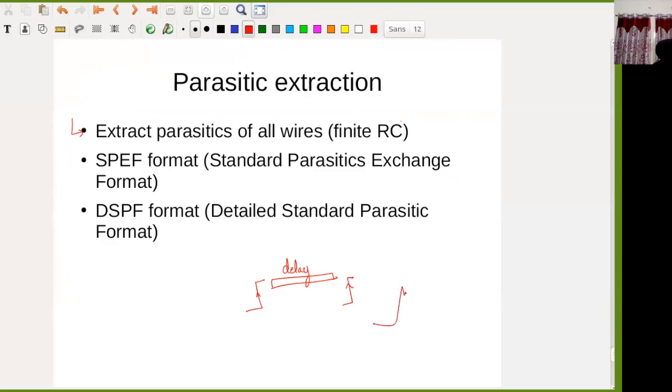So you might have overshoots, undershoots, and loss of signal quality, loss of edge rate, and so on. That is because it is going through a path, and especially if it is a high frequency signal, it is definitely going to have certain effects, which we will discuss later if time permits, called signal integrity issues.